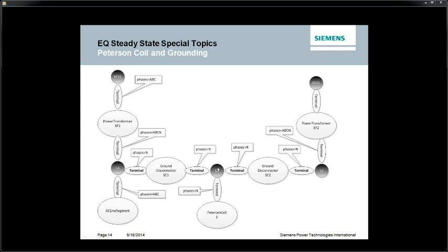Basically, you go through the CIM and find these devices, such as a fault isolator, a fault ground device, or a grounding impedance device. In this particular example, we have a Peterson coil attached to the C1 connectivity node via a terminal, with its phase set to neutral only. And this Peterson coil would then control the actual ground impedance that's available to these two parallel transformers.